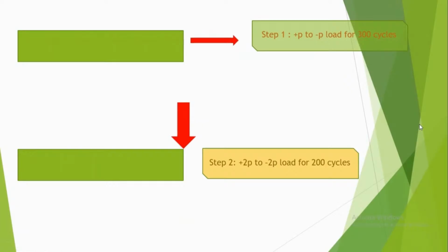But suppose your block cycle consists of two types of load that are completely different in nature. Then this method cannot be used because it just depends on the scaling of your amplitude stresses and your mean stresses. So you can't directly use FEMFAT basic to create the block cycle. So how do we create a block cycle in such cases?